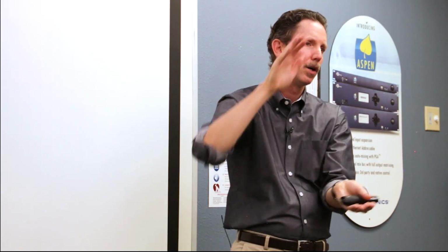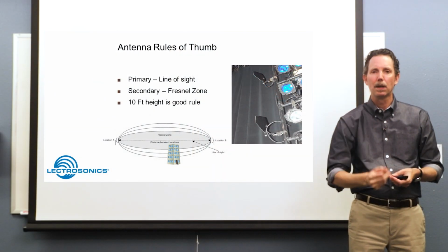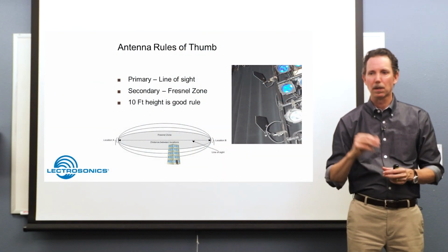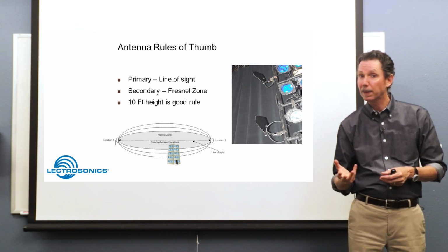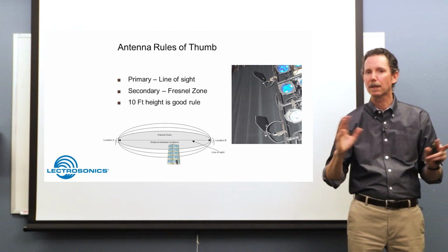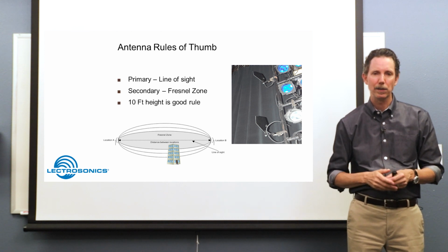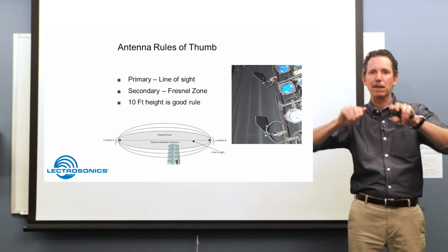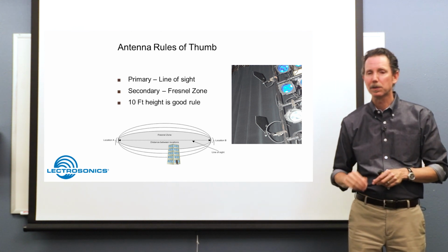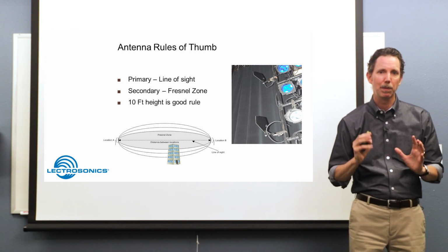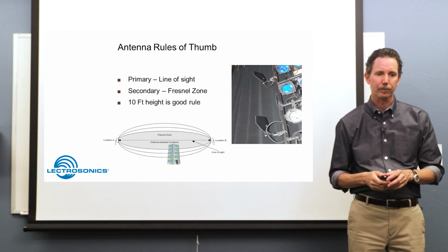This means that RF also doesn't travel like a laser beam in between your transmitter and your receiver antennas. It sort of has an envelope like a giant oval or a football, and anything that encroaches on that shape that's large, dense, again, people, cars, set pieces with a wire mesh, anything like that, can reduce the range of the system. So you want to try to keep that path as clear as possible so the RF signal has a good chance to get there and be picked up nice and solid.